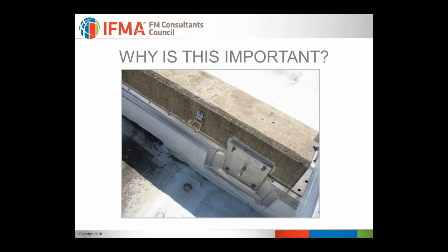In theory, we ran some numbers and it should work. The structure should be fine. The adhesive anchors were properly designed. Everything would be just fine. One flaw they did have was, you might be able to tell here, this is an eye bolt, and on the right-hand side of the screen is actually the roof edge. The idea is they would clip off their vertical lifeline to this eye bolt and go over the roof to do facade maintenance, which when they do that, they were going to load that eye bolt in sideways, which is not the strong direction of that eye bolt. So that was certainly a problem that they were going to need to correct. But beyond that, in theory, everything was okay.